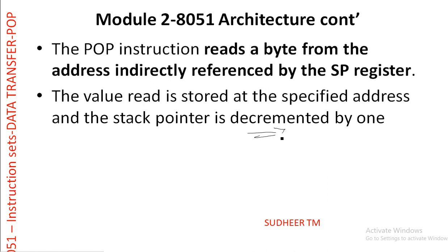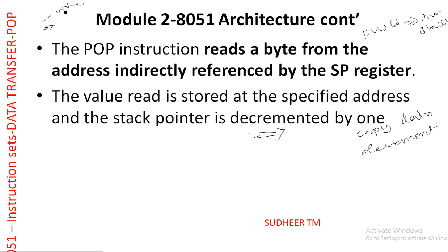Here, try to understand the difference. In push, the stack pointer is incremented before copying. In pop, the data is copied, then the stack pointer is decremented. It is like a notebook: if you have new information, you turn the page and write again. If you want to refer back, you read the page and turn the page back. Same like that: if you want to write, to push, SP is increased and the data is written right there. If you want to read from the stack, read the data and decrease the stack pointer. That is the operation.